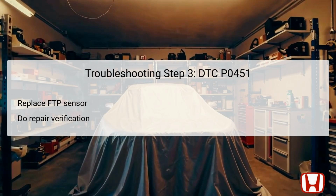Should the HDS indicate that the FTP sensor has failed, the immediate course of action is to replace the faulty FTP sensor. This replacement requires careful removal of the old sensor and installation of the new one, ensuring all connections are secure and free from interference.